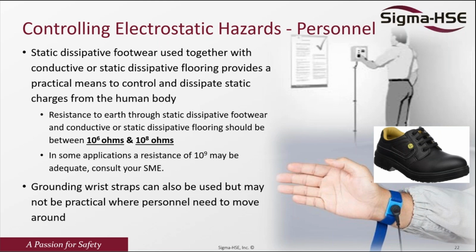Or you can have a grounding wrist strap, where you can tie it to your wrist. But the disadvantage is that if you move around more often, you cannot use this. And you always need to ensure you measure. Sometimes we might think that we have a static dissipative shoe, but actually the bottom is really dead, and in this case, we will not be able to get proper grounding.